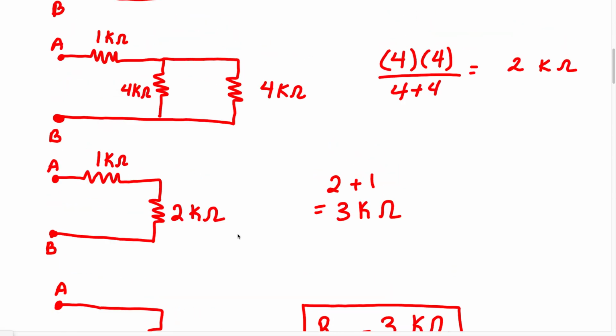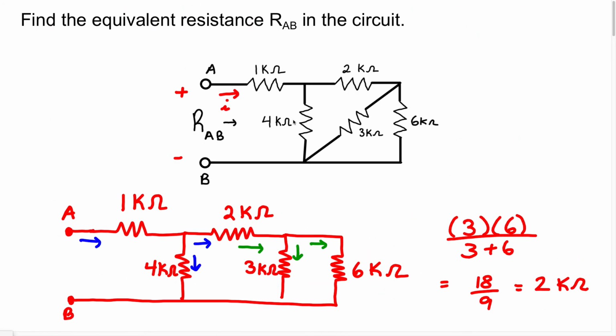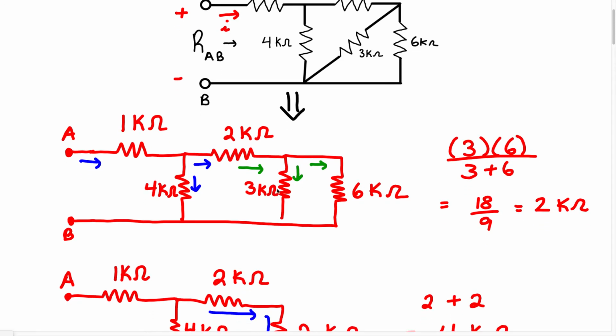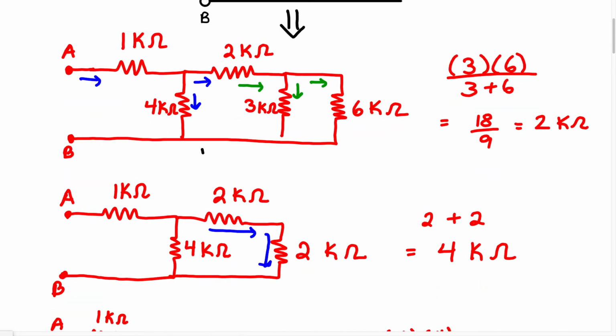So this is how you solve an example like this, right? We took our original circuit diagram and we said, this slanted line might give us some trouble. So we just redrew it as a vertical line. So we started off with this. Then we got this. Now that we drew it as a vertical line, we just started to simplify this circuit. We know these two resistors were in parallel. So we found the equivalent resistance for these two resistors. And we were able to simplify that diagram to look like this.